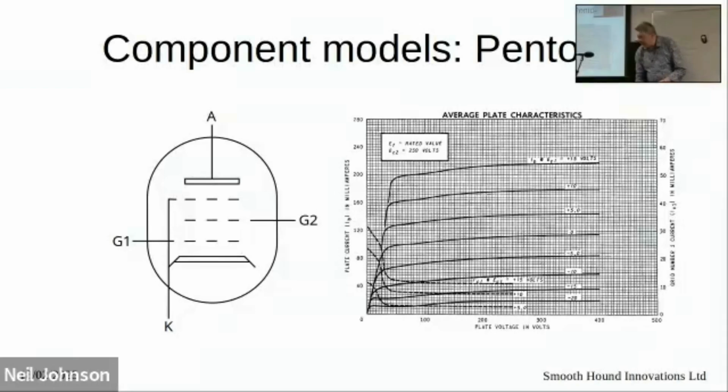We also, on this data sheet, again, it's not very common to have this, but we have data at positive grid voltages. So the plate current here is extended for positive grid voltages 0 upwards, and at the same time we then start to see some grid current. This is EC1 in here, and we start to see some grid current, especially as the anode voltage, again in saturation, rises.